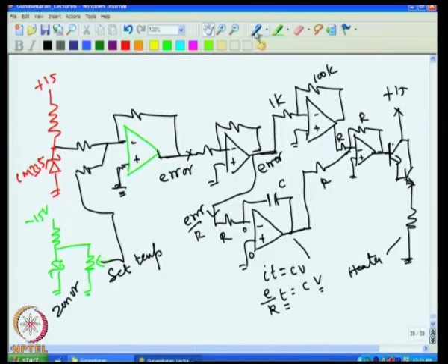So, the integrator was a good invention, but we always get confused, because with the integrator there, of course I can reduce the gain substantially, because even if the gain is lower, the error is not going to be there at all, because the integral action will take care of that.